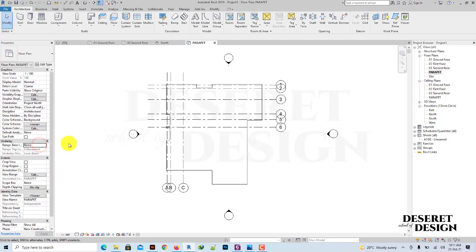We say underlays. Okay, it's not even set. So let's set it. Underlay, maybe I'm on the 10th floor. We show from our floor and base. You see, I have a parapet. So the only thing we can see is the shape of that floor. But maybe you want to see the wall. What do you do? You set the underlay to that particular floor and you see the wall. You see, I have a parapet.